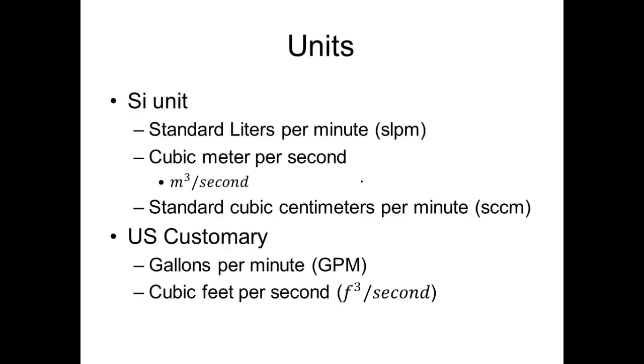You just live with the slight inaccuracy, right? Because barometric pressure basically changes every day, and temperature changes every day. So what you need to know is your mean temperature for the year, and also your mean barometric pressure for the year, and that way you can compensate your indicators for that. And then you just live with the slight variation during the days. Because if you didn't do that, what would you have to do almost every day?